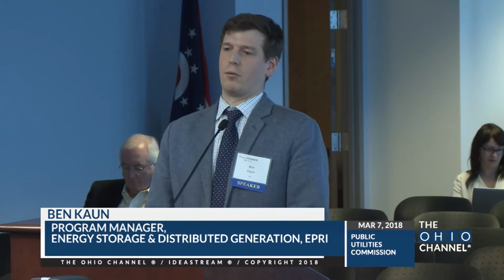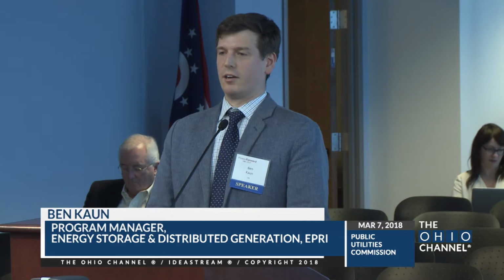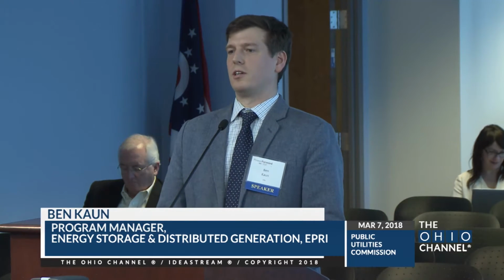But it is challenging because we need to understand if we're trying to create value. For example, we're going to build an energy storage plant instead of upgrading T&D infrastructure or instead of building new generation. There's reliability implications, so we need to make sure that the reliability criteria are being met before we try to stack on other benefits and squeeze more juice out of the device.